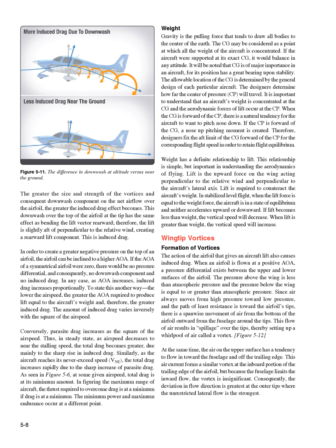This relationship is simple, but important in understanding the aerodynamics of flying. Lift is the upward force on the wing acting perpendicular to the relative wind and perpendicular to the aircraft's lateral axis. Lift is required to counteract the aircraft's weight. In stabilized level flight, when the lift force is equal to the weight force, the aircraft is in a state of equilibrium and neither accelerates upward or downward. If lift becomes less than weight, the vertical speed will decrease. When lift is greater than weight, the vertical speed will increase.